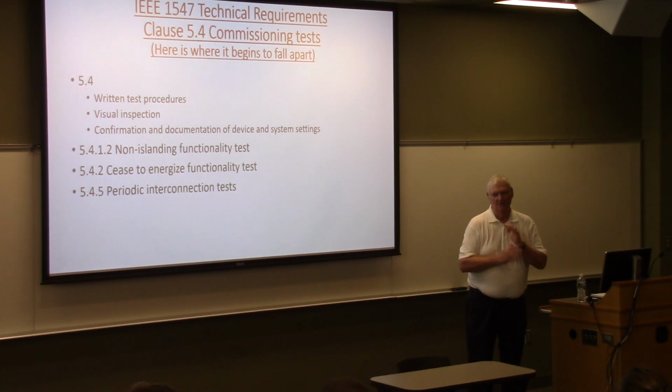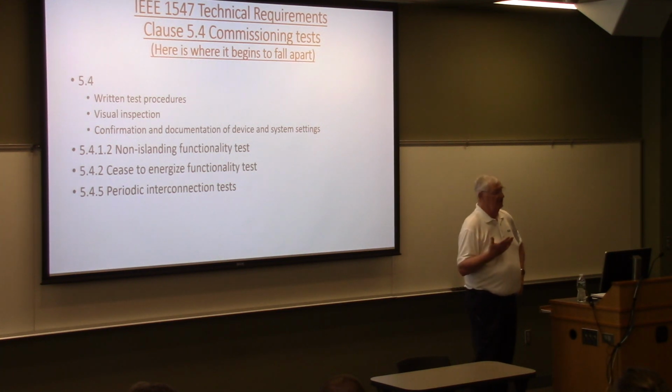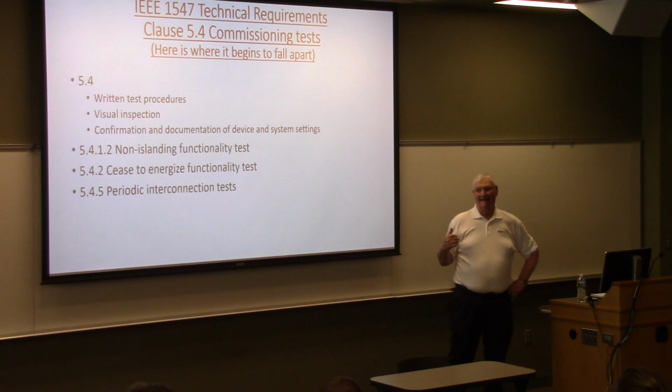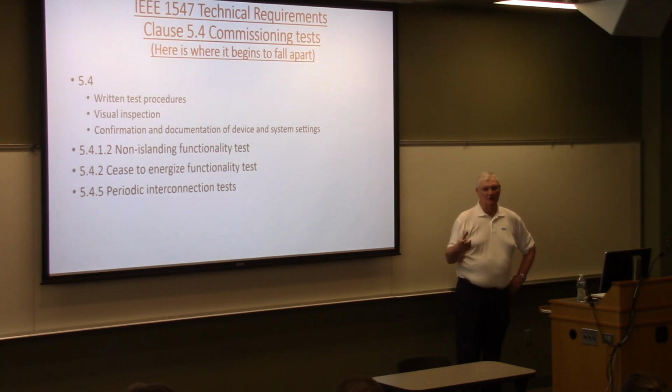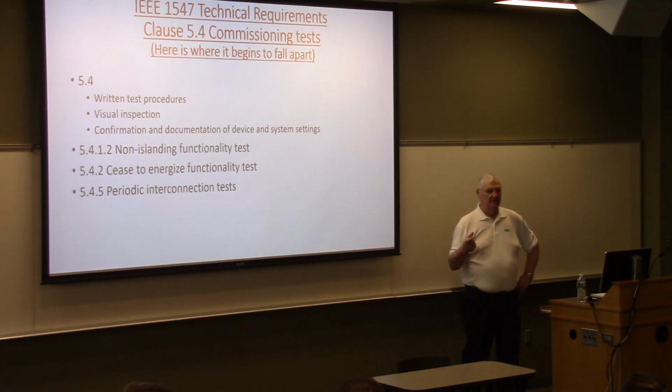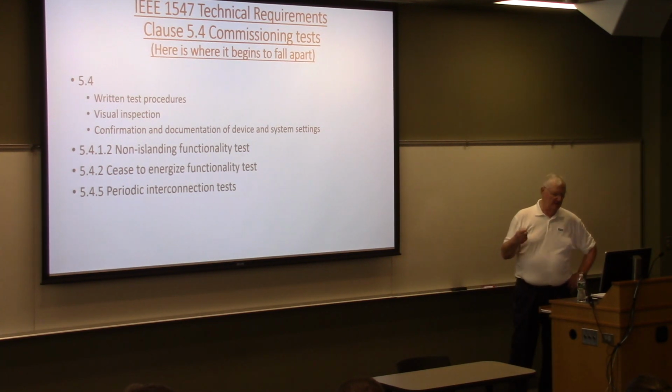One of the problems that I've run into when we're doing an evaluation of the system to see if it's functioning properly is doing a single phasing test, where you just open one of the feeders going to the system to see if it detects that single phasing. But one of the things that can trigger is called a ferroresonance situation, where the open phase, due to the capacitive coupling in the system and the inductance of the open coil of the transformer, can produce a resonant circuit that can give you voltages of 12 to 15 times the normal operating voltage. That's not good. So when we go to do these single phasing tests and so on, we need to do a real evaluation to make sure that we're not going to trigger a ferroresonance situation.